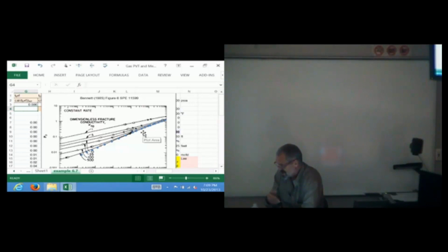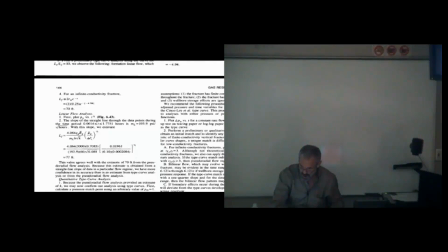Here, these tests are in hours. We usually see 6 months of bilinear flow, and that's because instead of being 0.08 millidarcies, we're like 50, 100 nanodarcies. Bilinear is when you only have flow coming into your fracture from one area, not from both areas, or what is really principally bilinear?